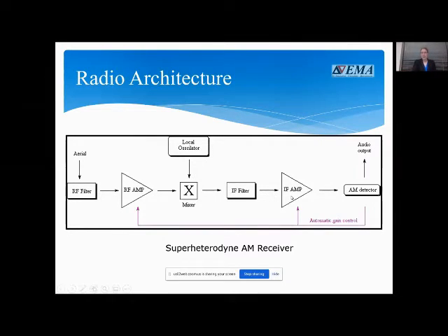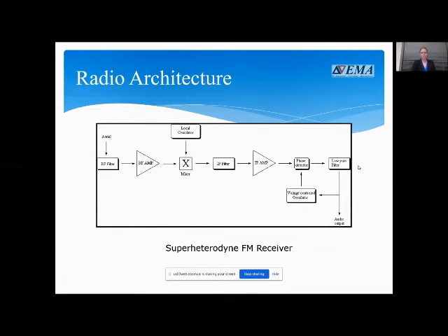And then you're going to amplify that intermediate frequency and send it on to the transducer that actually puts out your audio output. And so that's the path from beginning to end: you pick out the signal that you want, but it's still a range of signals. You mix it with the frequency that you've selected from your local oscillator to produce an intermediate frequency that's then amplified and sent to your output. Again, whether that's a screen or what you're listening to, or however you're receiving your signal.